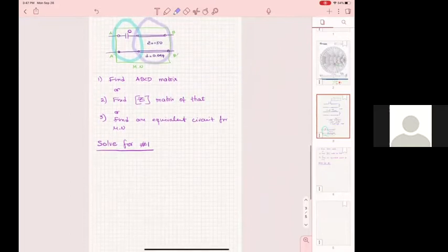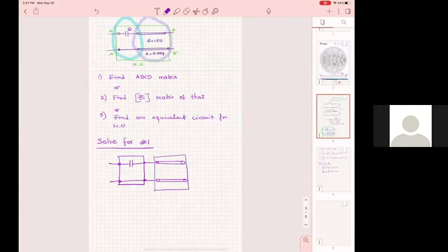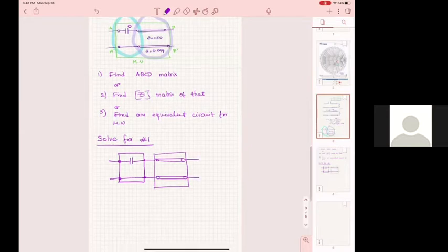If I do this, then practically I have one capacitor as one part of the network, connected with a transmission line as the second network. So the only thing I have to do is find the ABCD matrices of those two, and then multiply. Do you agree?